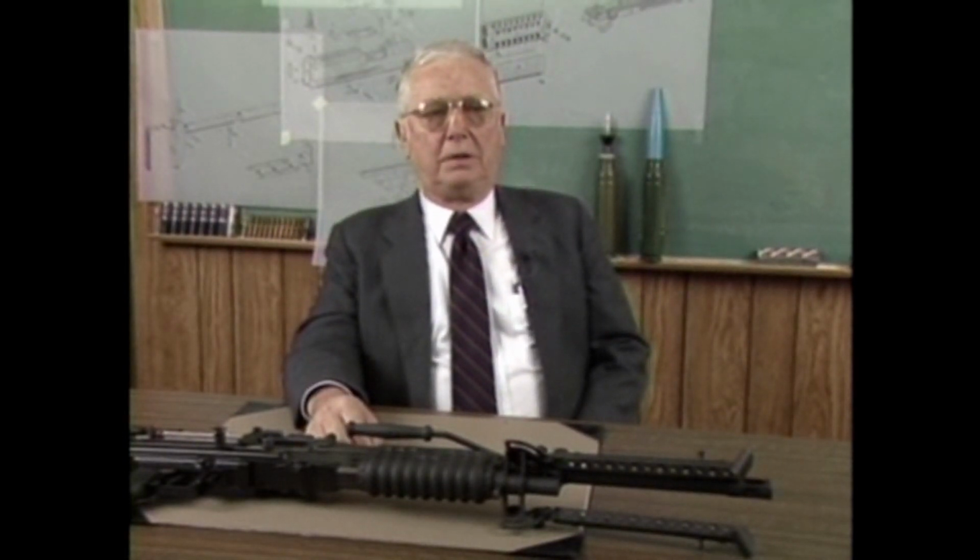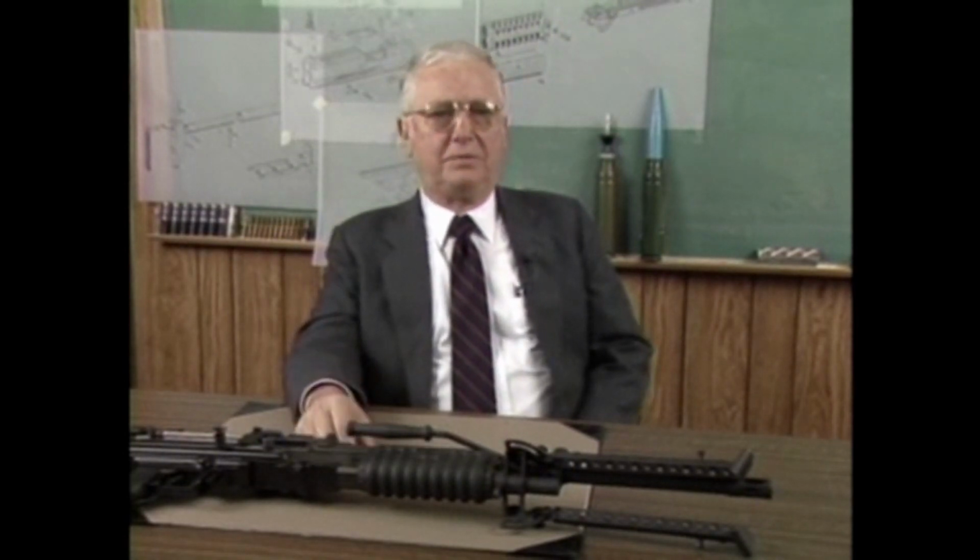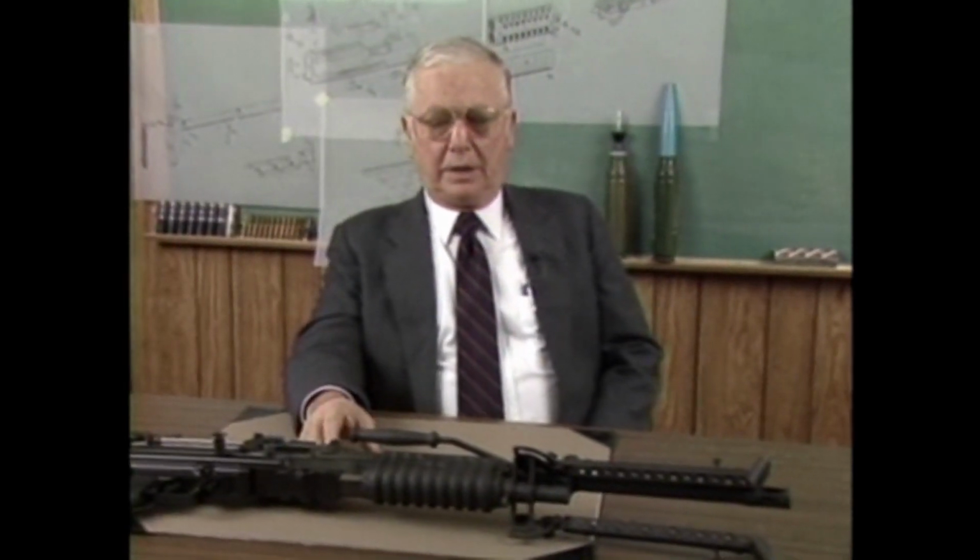Well, the largest caliber was the 25 millimeter automatic cannon I did for TRW, called the Bushmaster or the 6425 model. And the reason I picked it in the larger caliber was that it was a fairly low speed, low velocity type system as far as the bolt group is concerned. That system has the advantages of being very lightweight in overall weapon weight, easy to produce, and extremely strong as far as its weight is concerned.